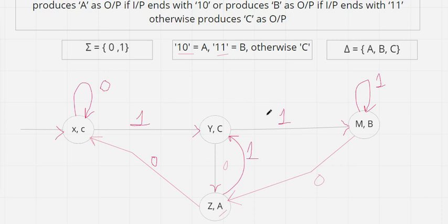So if it is done with the Moore Machine, now it is very easy to understand how to construct a Mealy Machine, correct. So I can look into transition number 1, which is this self loop for 0, where it is entering state X, which has the output C. That means the output for this will be C, okay. So next, what is the incoming edge? This is another incoming edge, so this output will also be C, okay. I think it is clear.